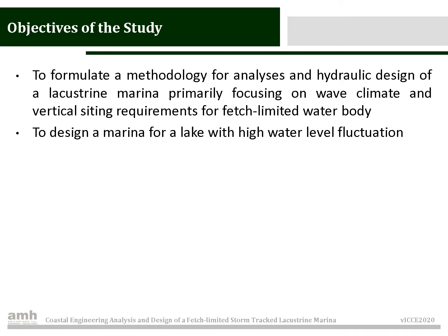The objectives of the study are to formulate a methodology for analysis and hydraulic design of a lacustrine marina, primarily focusing on wave climate and critical siting requirements for a fetch-limited water body, and to design a marina for a lake with high water level fluctuation.